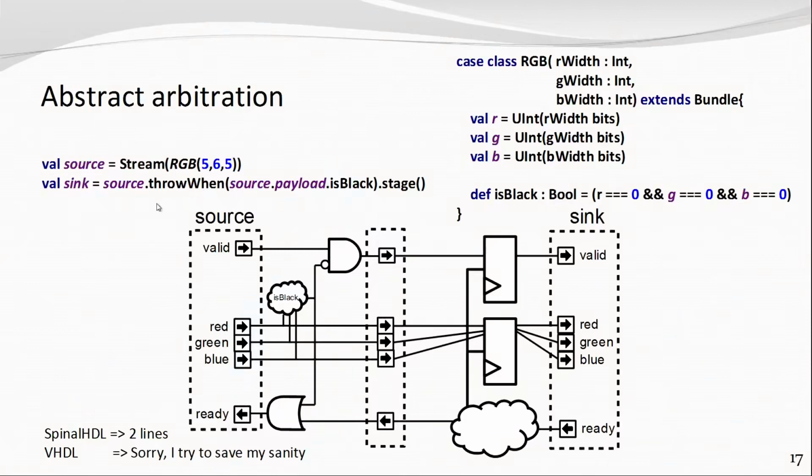Then you can take a look at the generated VHDL if you are really not sure and there is something strange. The generated VHDL is not crap. It is readable. If you search for your signal name, you will find it. It will still keep the same name. If you use a statement, you will still find it in the generated VHDL. So it is not a mess. It is all right. But normally you don't have to go into the VHDL. You will still have points where you can probe signals, and that should be all right.